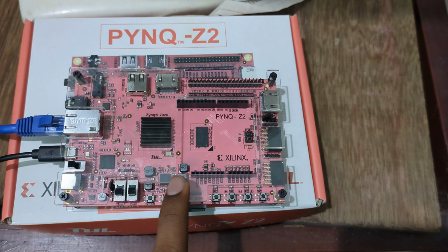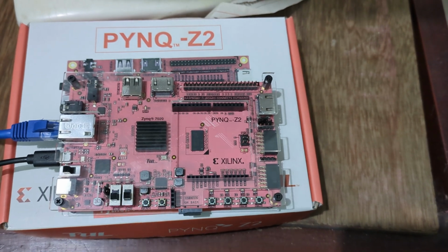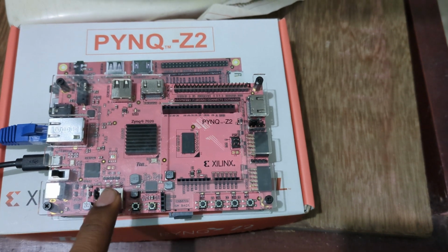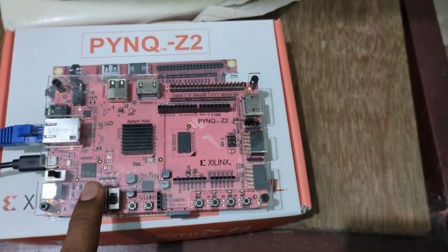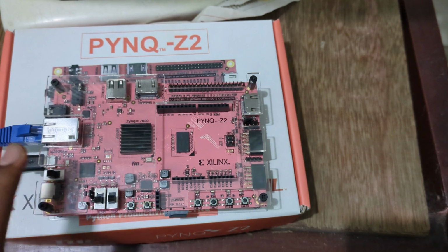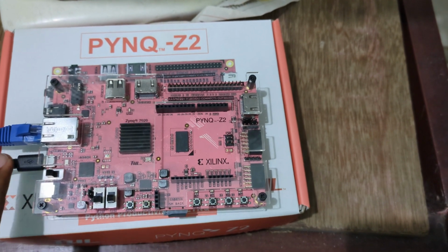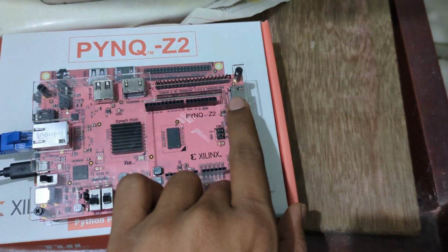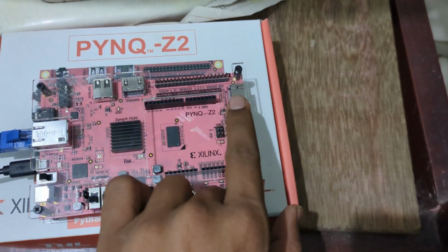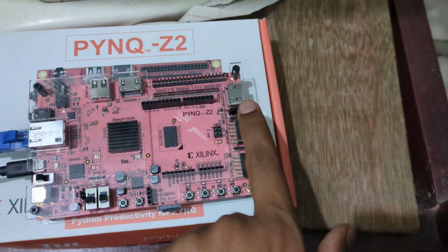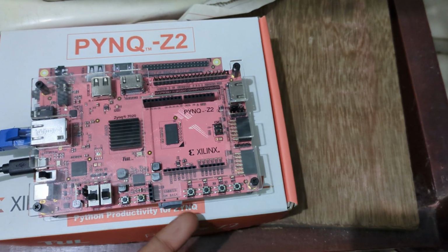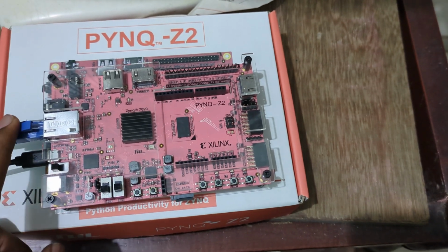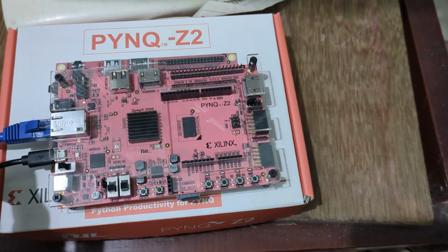First of all, we have got jumpers here which we have to set appropriately. Here we have put it in the USB slot, and the USB slot is where the board is going to get the power from. We are going to give it to the USB slot here, and this USB is connected to the laptop or any other device. And here there is another jumper. Here we will say where the memory is and where we have all the resources. For that we have put it on SD card, and we also put the SD card into the board. This Ethernet cable is also connected to the laptop in this case.